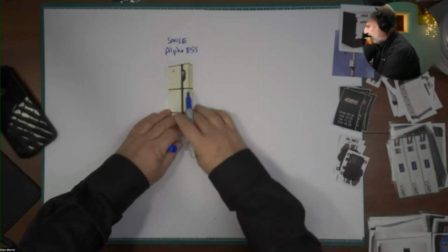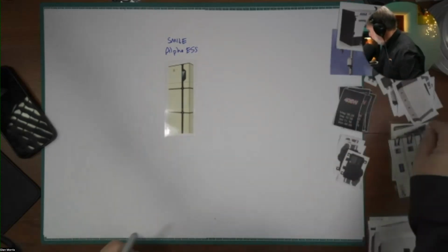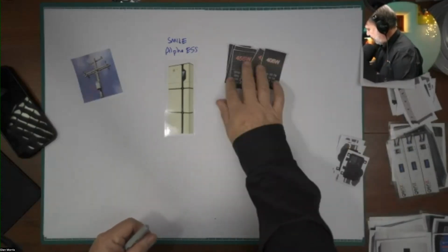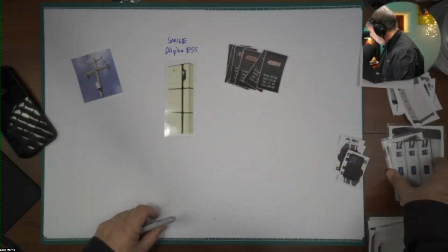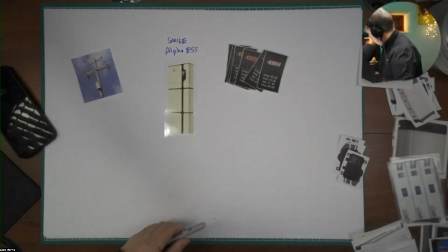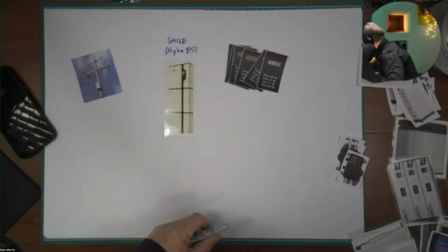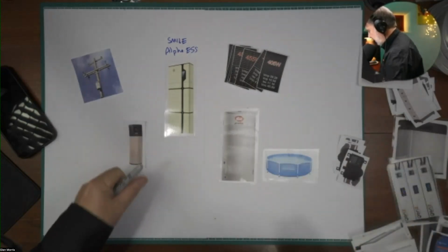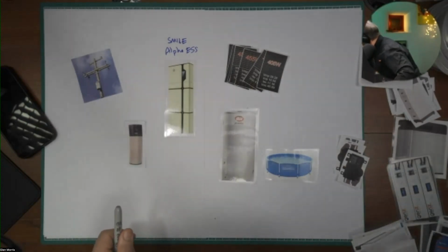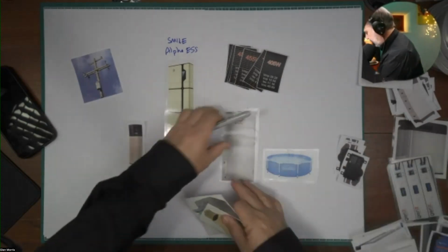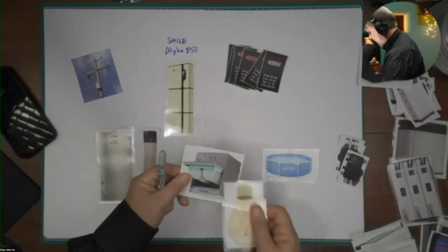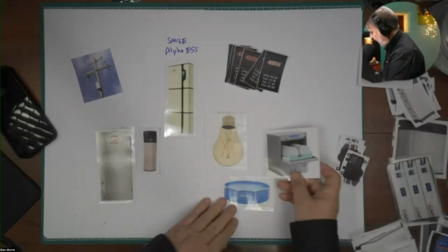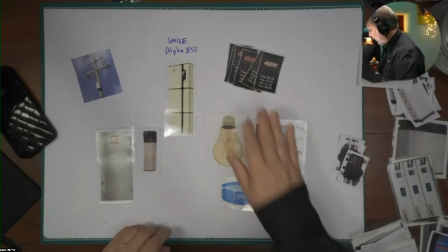Now, what makes it a hybrid inverter? A hybrid inverter can have the grid connected to it. It can have solar panels connected to it. It can have some loads connected to it, some loads which are on the grid side, and some loads which are essential. Now, this is not always the case. Not all hybrid inverters have essential power, but it's pretty common these days.